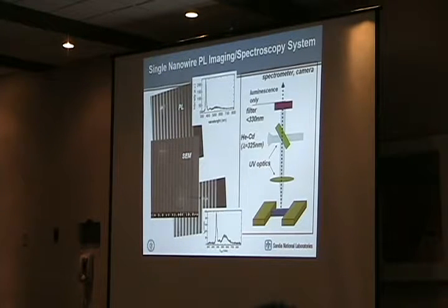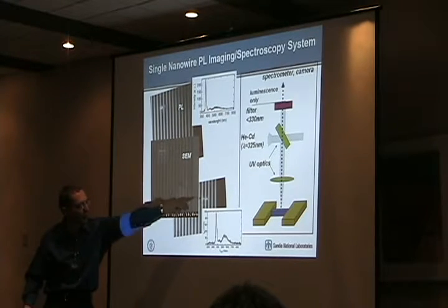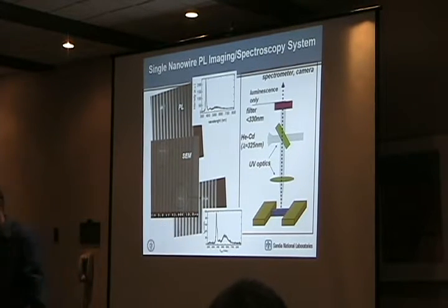So now, what I was just telling you about the electrical properties of these nanowires. We're also very interested in optical properties and how they relate to growth and the electrical properties. And so what we do is we just use microphotoluminescence. So we have a probe station and micro-PL using a helium-cadmium laser. And of course, our platform is ideal for zeroing in on the nanowire. You can see the photoluminescence image here, and you can see the spectrum right there.